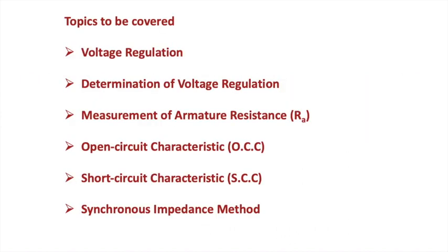So the topics to be covered today are the definition of the voltage regulation, then determination of the voltage regulation, then the three major requirements: measurement of armature resistance, open circuit characteristics and short circuit characteristics. And the synchronous impedance method is the first methodology to calculate the voltage regulation.